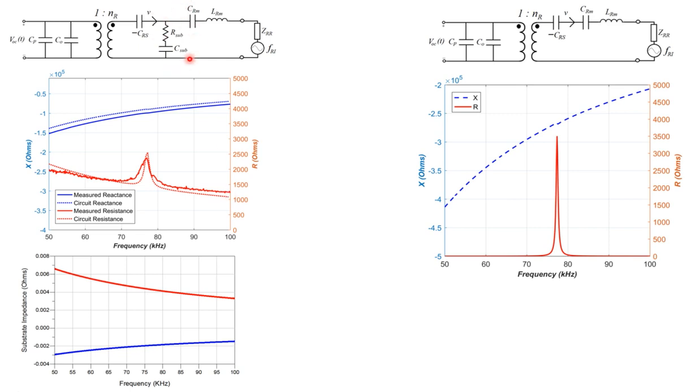If you don't have this loss with the transduction force, so this is a linear model. The transduction force is linearized in terms of electromechanical coupling, turns ratio, and the spring softening capacitance. If you don't have this shunt loss with the transduction force, like over here, where we have open circuit conditions for, say, a rigid backing or a solid backing, then you don't have the baseline. It's not just the baseline, but I would say the loss is notorious enough to reduce the measured quality factor. You see the quality factor is very different in these two models. And what the measurement suggests is that you have those kind of baselines.